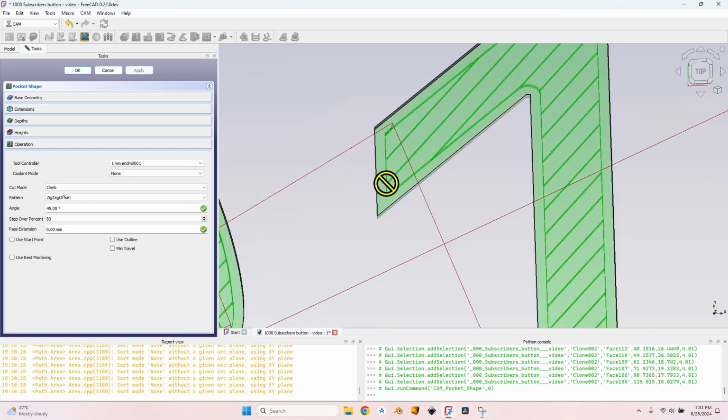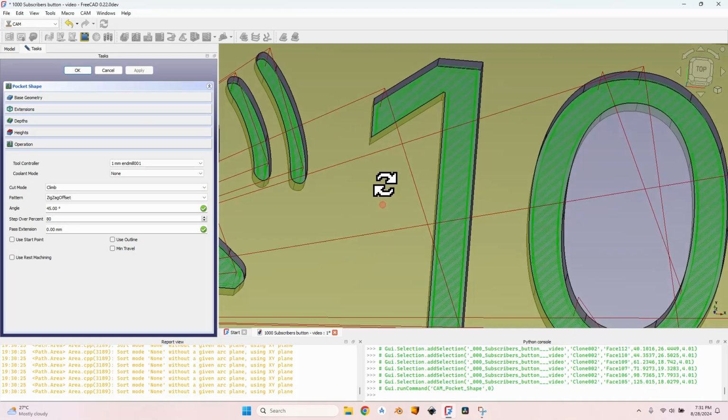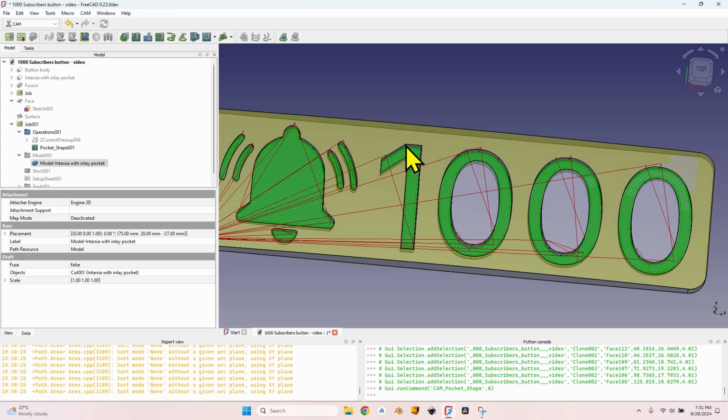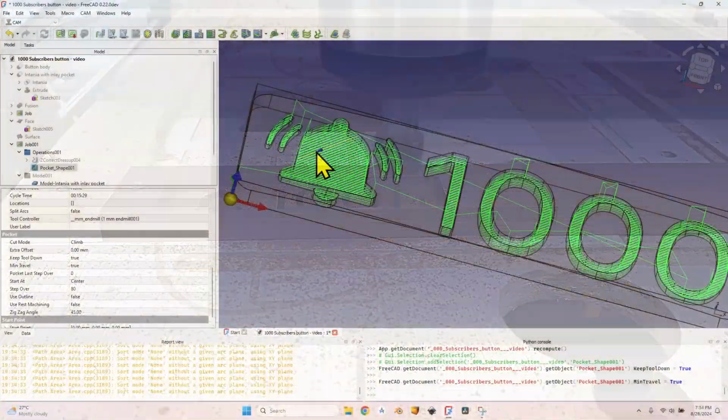Even though the toolpath is with a square corner, of course using an end mill will result in a roundover. This wouldn't be a problem if I didn't have to fit another piece inside of this one. To solve this problem I am going to have to edit the sketch and add some fillet for these corners, for the sharp corners, in order to avoid any problems when fitting the two pieces together. And now everything should fit.